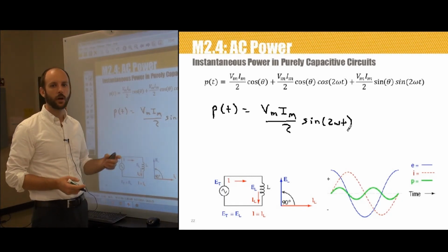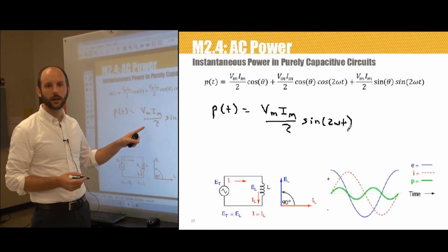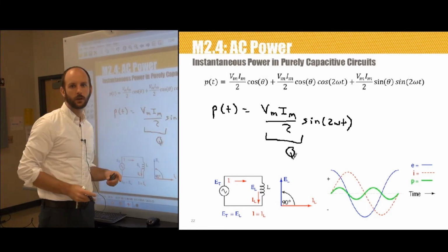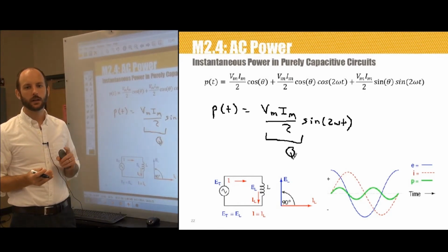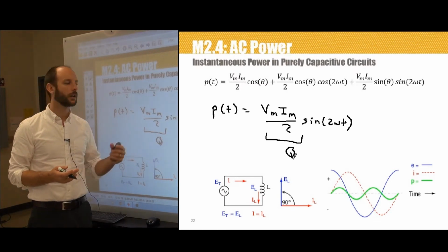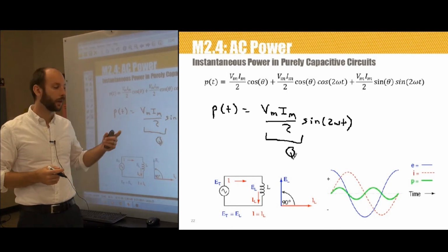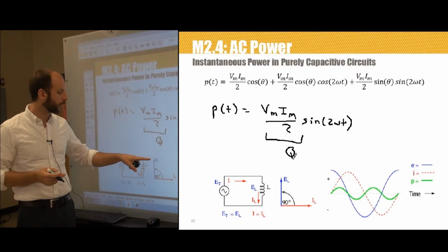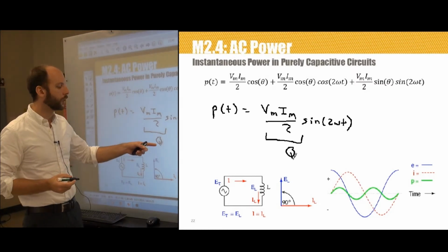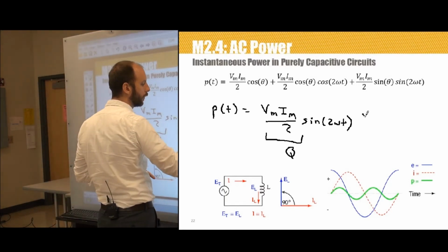The measurement of power associated with a purely inductive circuit, we call that Q value here. It indicates that the power is associated with the reactive circuit element. So you see the Q came into play with the inductor here, and then in the previous example with the capacitor. To distinguish the reactive power from the real power, we use a different unit here. It's called volt amps reactive.